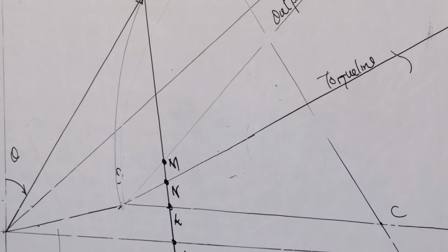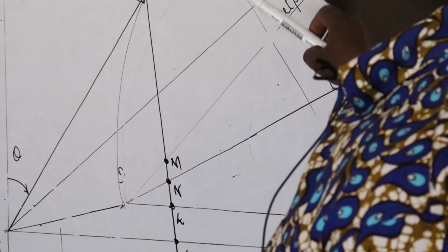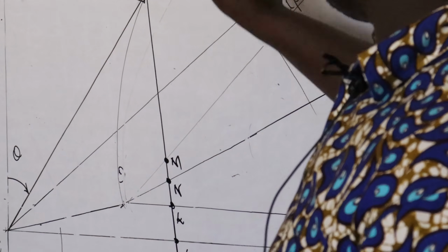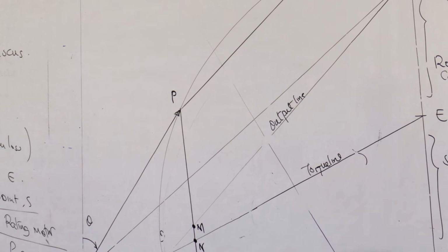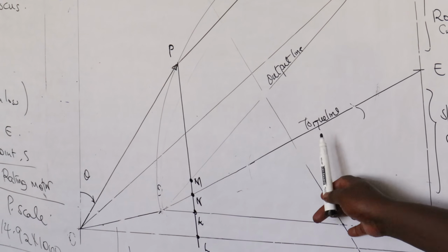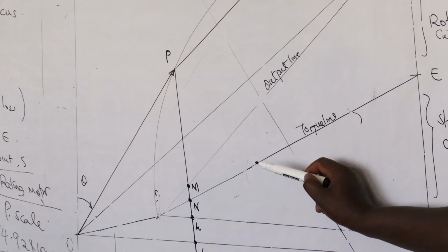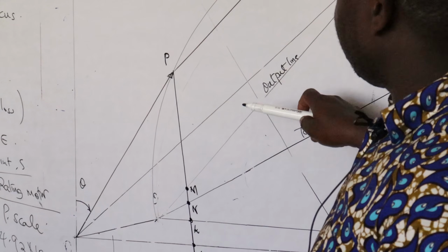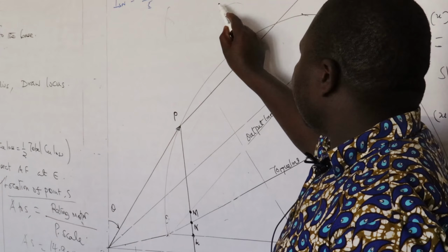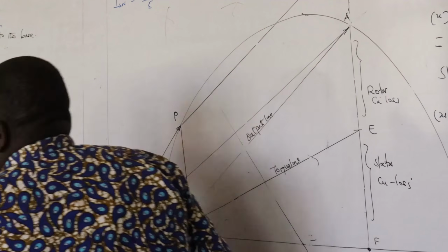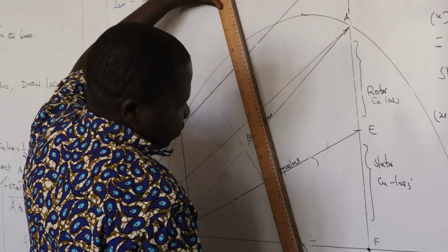Are we there? Yeah? Then extend those arcs. While you are standing at this arc, you draw that. Let me repeat. While you are standing at C, make an arc, right? Then the other arc, the other side, right? Then on the same arcs you mark, extend your compass and cut and make an arc and cross that arc. Then drop that point back to C.